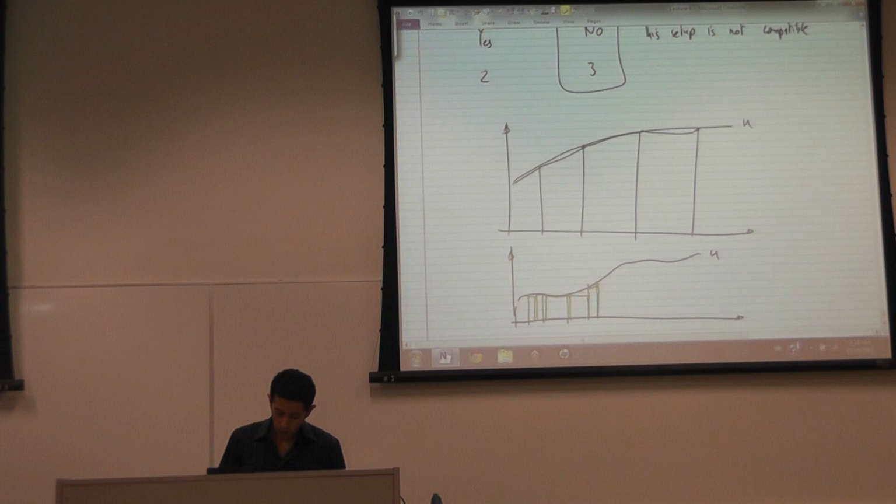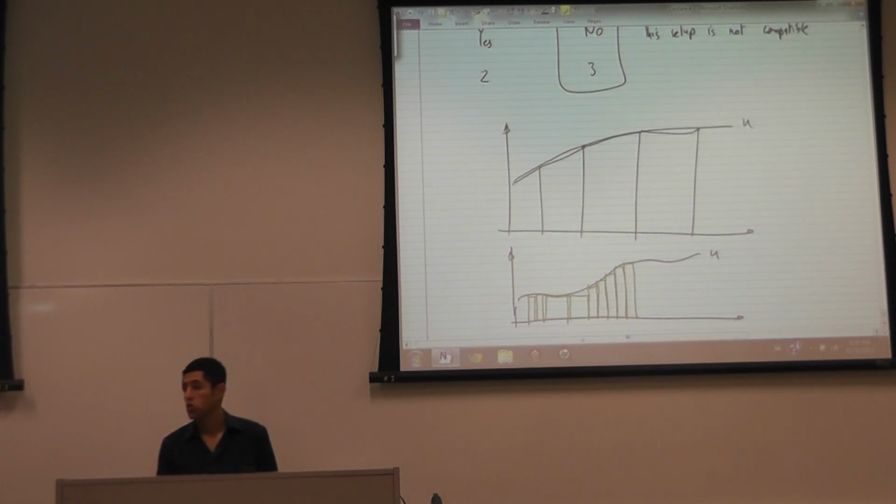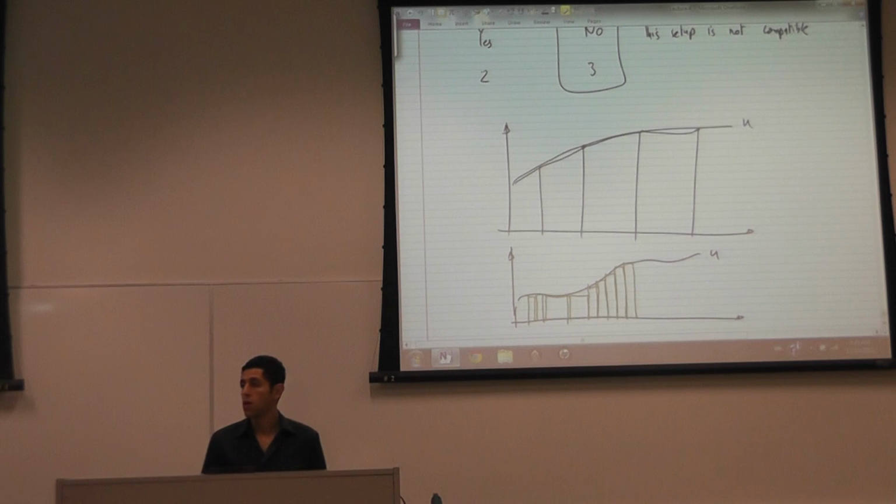If you model elements that behave just having constant displacements on the element, or constant pressure, depending on what you're solving for, these are incompatible. If you will, the constant strain triangles, for example, like all the finite elements that we use, are incompatible when it comes to the strain, because the strain is not continuous.